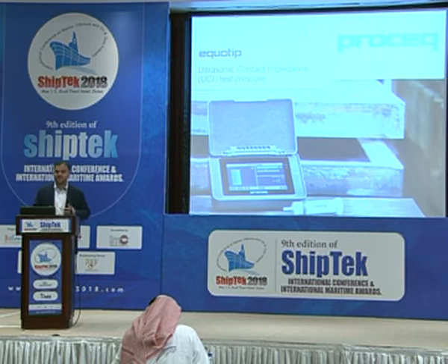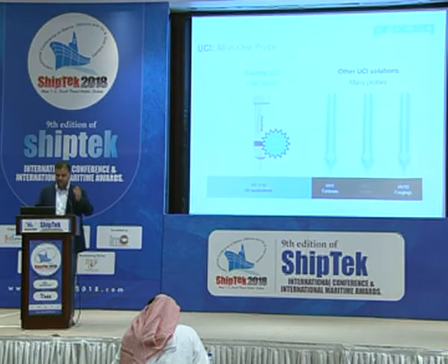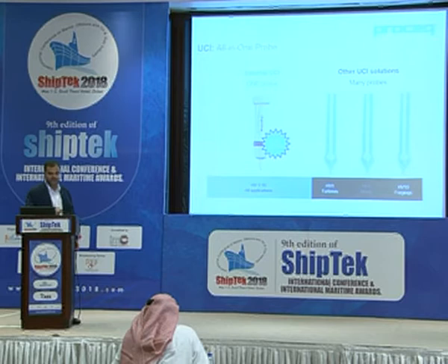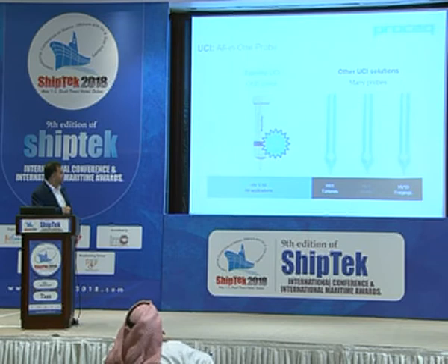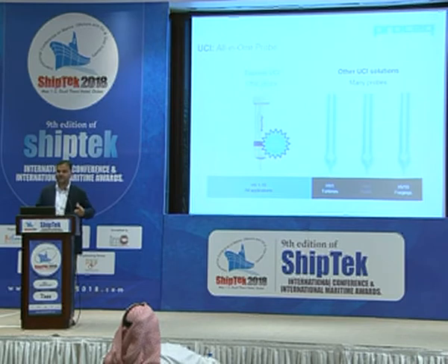And the third established technique for hardness measurement is the UCI, ultrasonic contact impedance. Again, a non-destructive testing method. In the industry, we have always seen several probes offered for UCI solutions: HV1 for turbines, HV5 for welds, HV10 for forgings or castings. But now we are offering a new technology, developed to have the same probe with selectable loads. It comes with only a single probe with selectable loads, HV1 to HV5 and then HV10 as well. So we can just select the load in a drop-down menu and we are good to go.